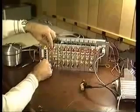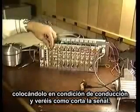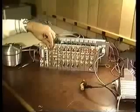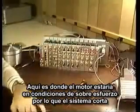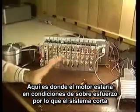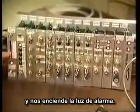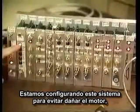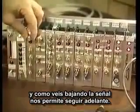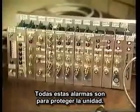Alright, let me take the inhibit off. We'll put it back in the trip mode and you'll actually see it shut down. And there's where the engine would have gone into an overspeed condition and we shut the electronics off, therefore allowing the safe operation of the car. We have an alarm light on. We're sitting at a high tach. We had an overspeed trip. If I bring the system back down, I'll allow it to cut back in. We have all of these alarms set up to protect the unit.